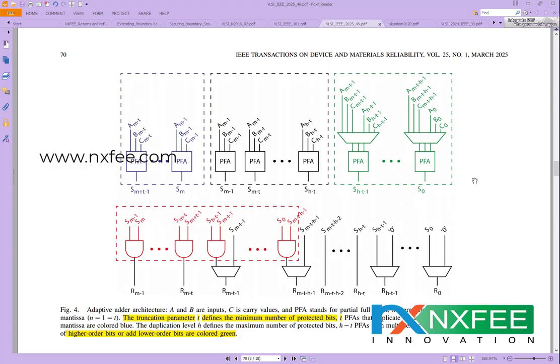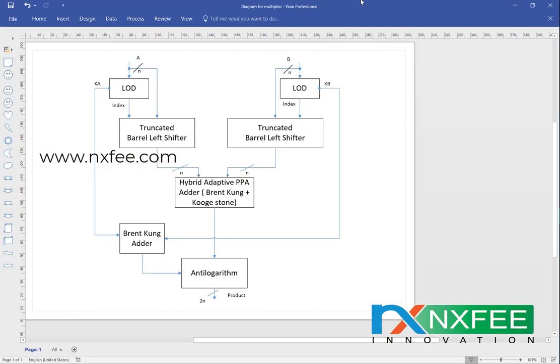This adaptive adder is designed with a ripple carry adder and carry lookahead adder method, and these are basic methods. They are not well balanced for speed, area and power stability. A new hybrid adder technique is designed with Brent-Kung and Kogge-Stone based architectures for this proposed method.